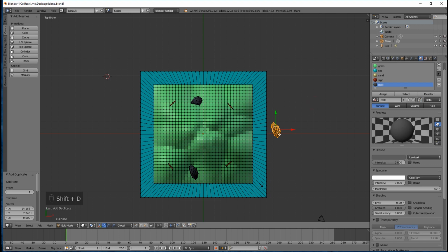Of course, I've distorted the original rock. What you can do if you want is to keep your original rock off to the side, duplicate it each time, and move it into position. And then once you've got the final rock, you can either move that into position and that's it, or just delete that rock by pressing the Delete key on your keyboard. So you've got your basic template always kept off to the side. That's entirely up to you.